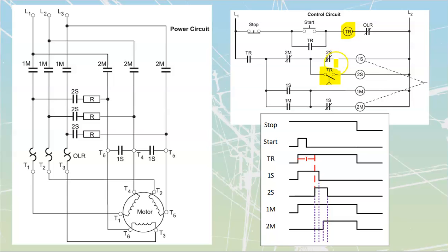So let's go through this timing diagram development, and then we'll start applying it to the actual power motor diagram. We're going to start with the start button. That's what we always do. We can also start with taking our power and just putting it through on our controls up to where we know that it's going to be stopped by open sets of contacts. So the second that I press my start push button over here, power is going to pass all the way through here, and I'm going to seal that in through an instantaneous contact off my timing relay.